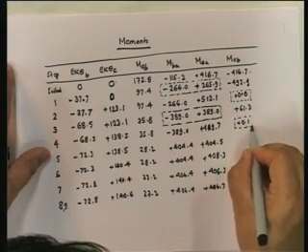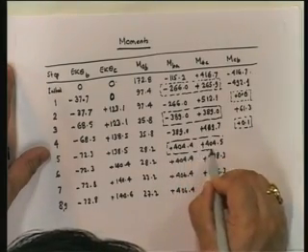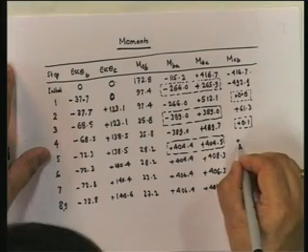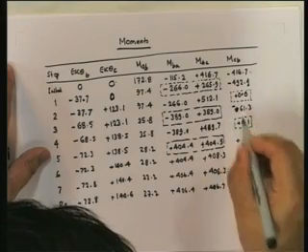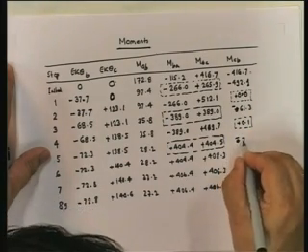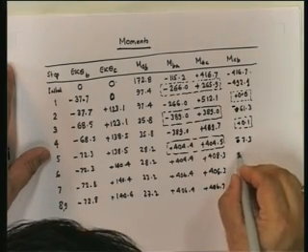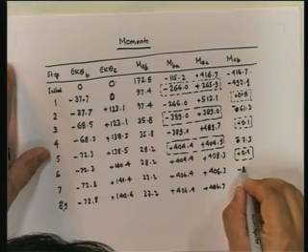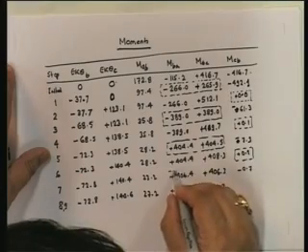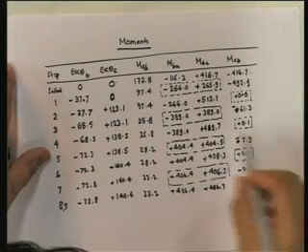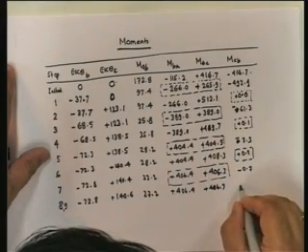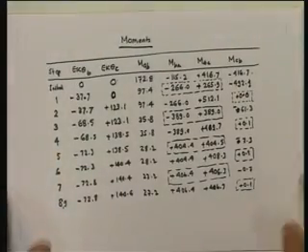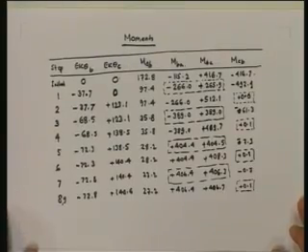So this is where you're releasing this. Then the next one you're releasing this, and so you get, I'm so sorry, here you get minus 7.3, here you get plus 0.1. This is the one that you're taking to 0. Then you get minus 0.7. This is where you release theta B, so alternately you're releasing theta B, theta C. Finally you have plus 0.1, which is the release. This should actually go to 0, but we have a least square. Now, this is the solution that you have.